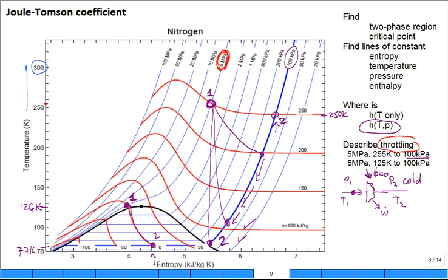And then you're going to go into two-phase region, and guess what? Your temperature out versus your temperature out before, they're the same temperature out, 77 Kelvin. Oh, you still have more liquid to vaporize. But in this case, the turbo expander is not as valuable. The first case is huge. Can you see that? Even a poor turbo expander would be great. All right.